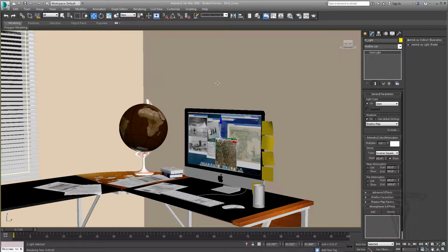I'm going to go ahead and cancel this. I'm going to set this to none. Another way is to use far and near attenuation. All right, so I never really use near unless I'm doing some kind of special effect to the light. In this case, we're not. So I'm going to just use far. So I'm going to click Use and Show. Now what this does, I'm going to turn off Show here so I'm not seeing that little blue wireframe.